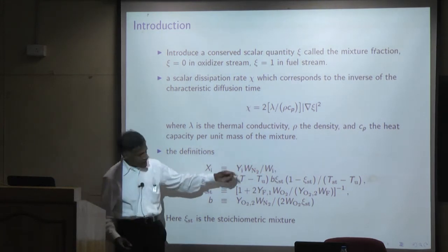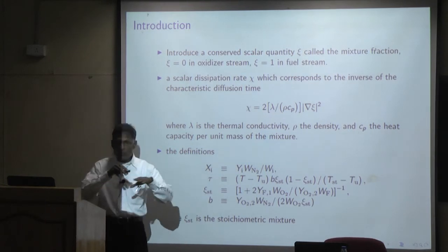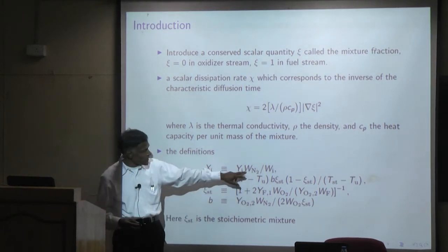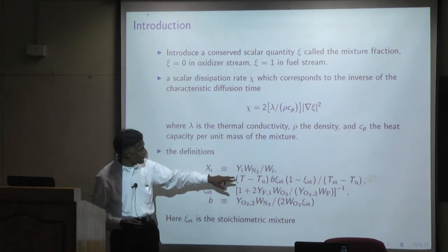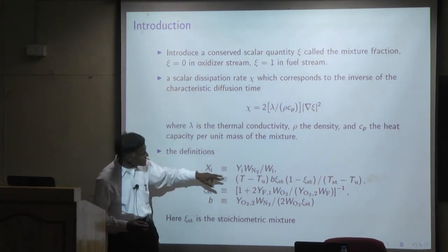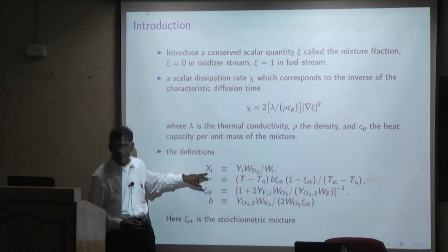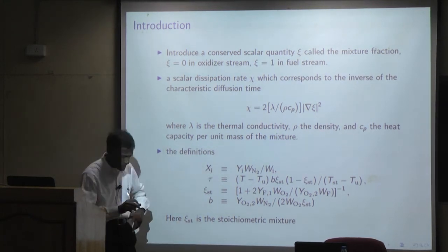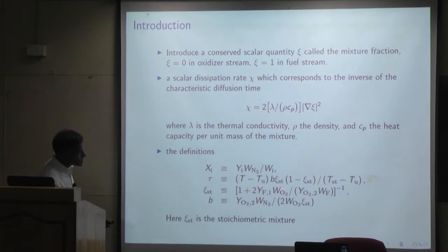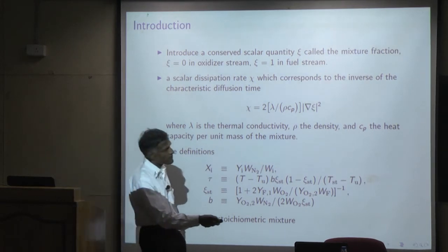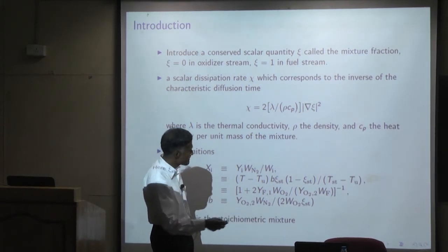In combustion mixtures, the average molecular weight of the mixture is very close to that of nitrogen, N2. So even though this is a normalized mass fraction, it is actually very close to the mole fraction. It's not the mole fraction, but it's very close. And that's the non-dimensional temperature. This is the stoichiometric mixture fraction, ZST. That's where the flame is located, right there.